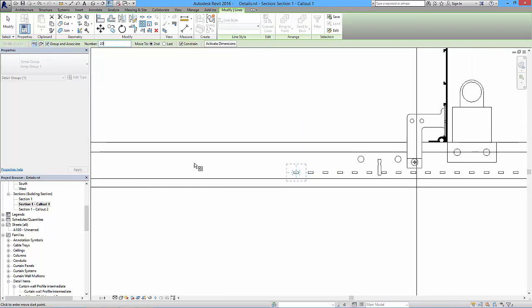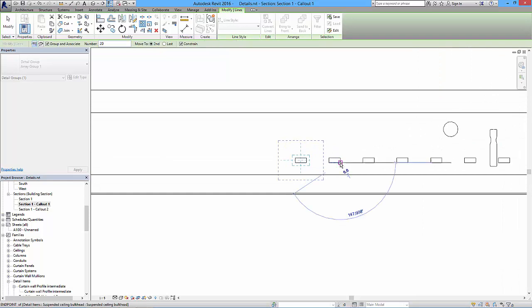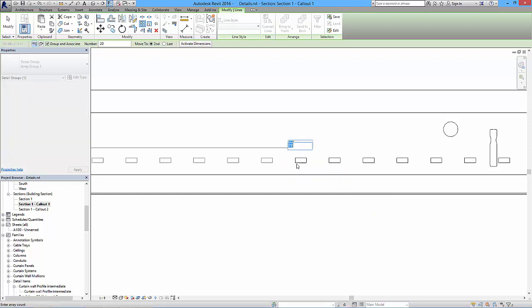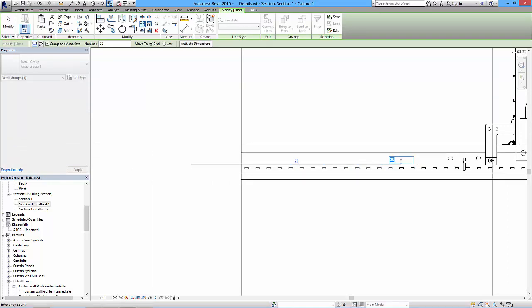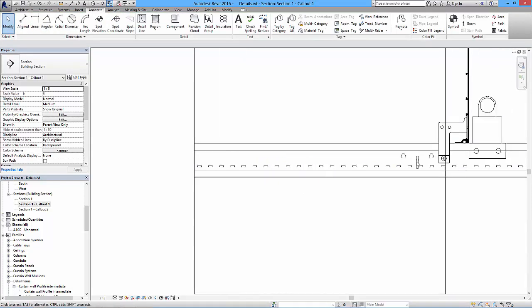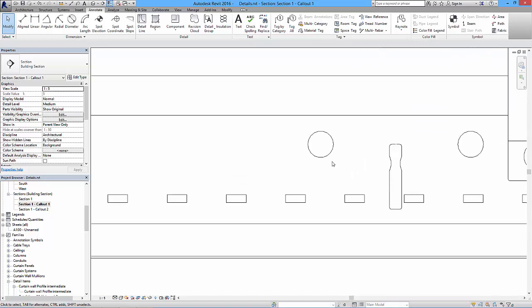If we group and associate for now, then it means that we can adjust that later on. So if I zoom in a bit and pick this point and copy it to that point, so basically this is my move to second from there to here, and then that's going to array that, and that's taking it down there, so I don't need 20. 15 would probably be sufficient.